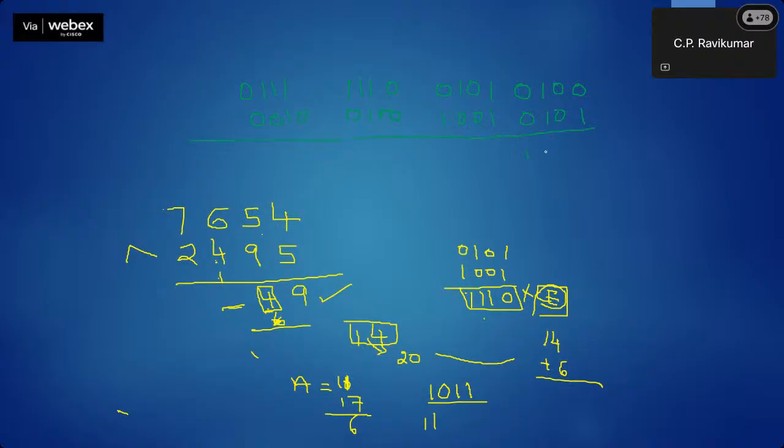So when you added these two, we got 1, 0, 0, which is a valid BCD digit, so no problem. When you added these two, you got 1, 1, 1, 0, which is unfortunately not a BCD digit. So we are saying add 6. That will cause a carry to come here. So the corrected value here is 4, and this value is already 9. It's the correct value.